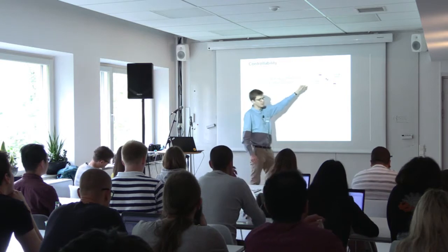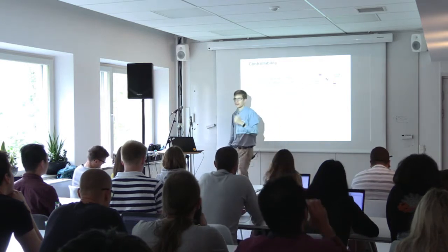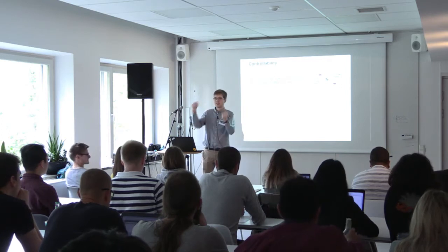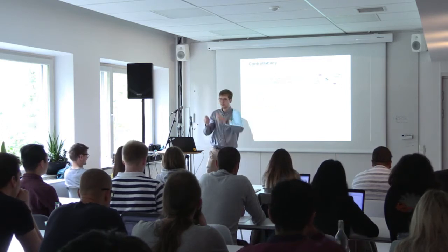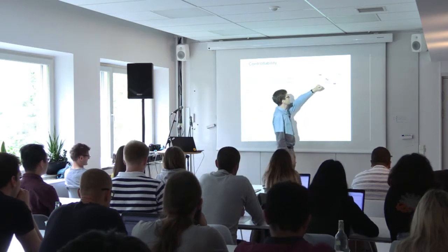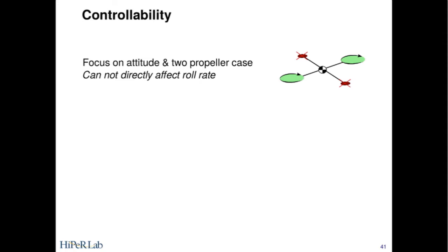Here it's kind of interesting because it's not intuitive how this works, right? When we had this 2-dimensional quadcopter yesterday, it was very easy to understand that if I create a torque that rotates the thrust direction, it allows me to push the vehicle around. For this 2-propeller quadcopter, it's clear that if I want to rotate around this axis, I can use a differential force, right? So if this propeller produces more force than this, the vehicle will rotate in that direction. But there's no input to cause the system to rotate around this axis here, which is the harder part of this.